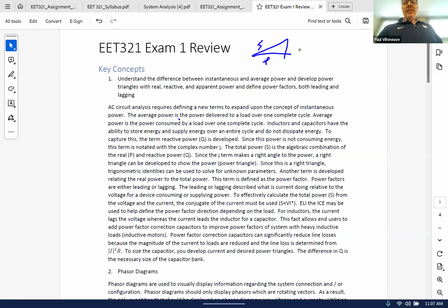So here's P and S, and here's theta. And we defined our power factor to be equal to the cosine of theta, which is equal to P over S. The power factor is really defined as the ratio between real power and total power. And the trig identity, Oscar had a heap of apples, says it's the adjacent over the hypotenuse. So it's just a trig identity. That's the reason why we do the cosine. It's always the cosine because the trig identity dictates what we use there.